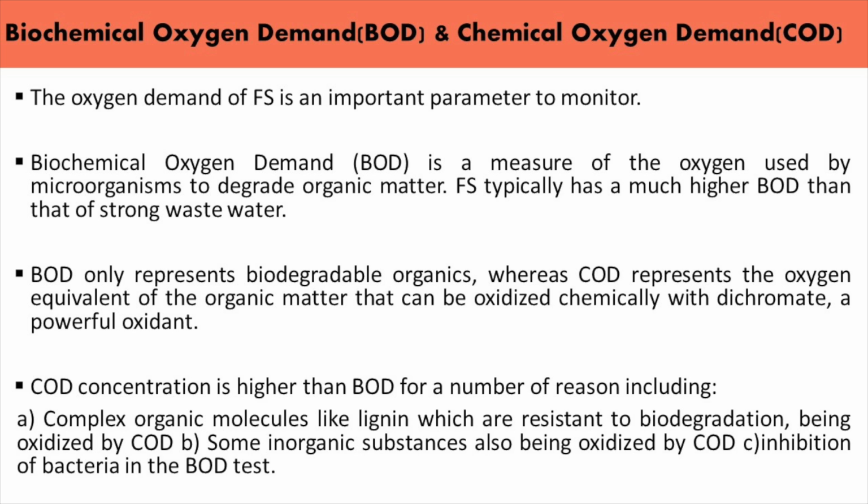Another reason is that some inorganic substances are also oxidized by COD. The next one is inhibition of bacteria in the BOD test. COD is determined in the laboratory with an open or closed reflux method and also through commercial kits. The ratio of BOD to COD can also be used as an indicator of the relative biodegradability of the organic matter in different waste streams.